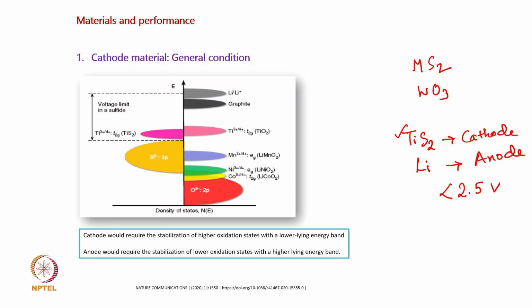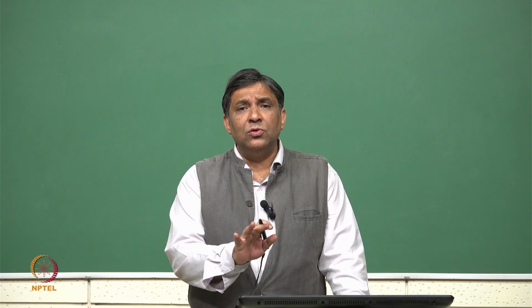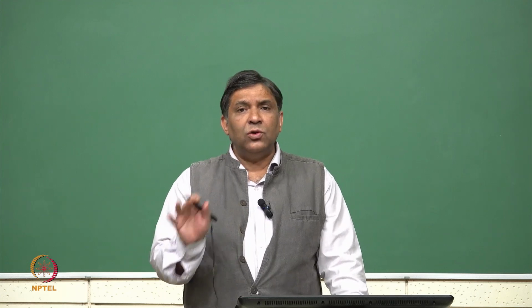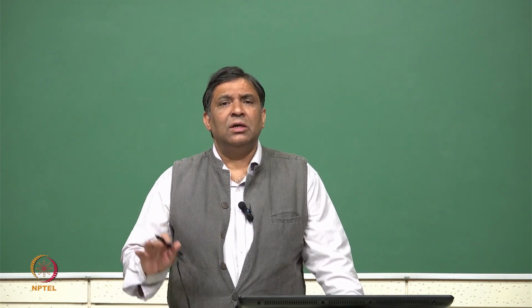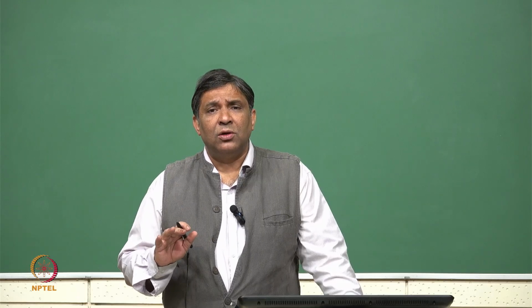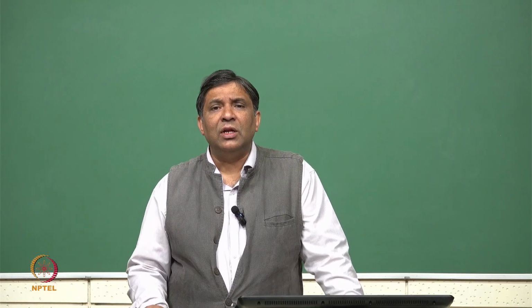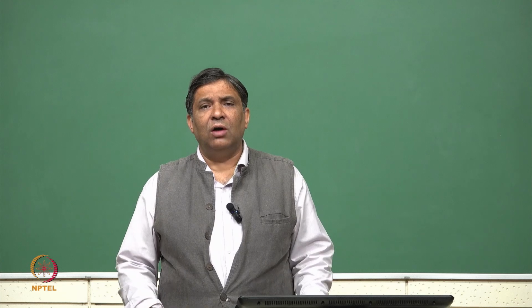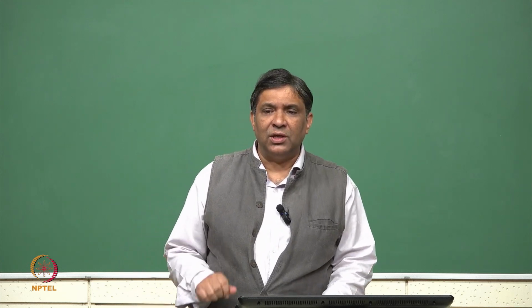Okay. So, then people started working with different layered structures, and they also realized that lithium as anode is not good because there are certain problems. There is something called the dendritic issue, which can lead to a short circuit. Okay. And then one research area was going through what is the best anode material that one can choose, and people found that graphite could be the best material because it is also a layered structure and intercalation of lithium can be possible in the graphitic layer.